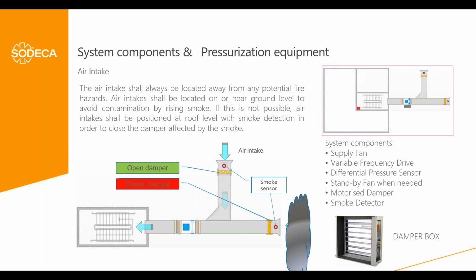The point is that maybe it's not necessary to have two independent air inlets for each fan. We can have a plenum for the air inlet of the whole system, let's say, of the lift shafts and the staircases, and from that plenum we can take the uncontaminated fresh air to provide on one side the lift shaft and on the other side the staircase. So it's not necessary to consider two independent air inlets for each space. Maybe it's possible to do it with two independent inlets for the whole pressurization system.